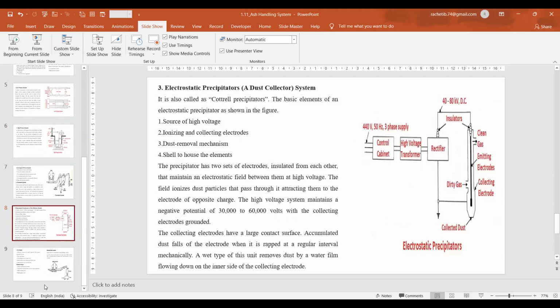Now the most important one, the electrostatic precipitator, which has an electric field causing ionization of the ash while flowing from the economizer and air heater into the electrostatic precipitator. The flue gases separate into positive and negative ions, ash, with the help of this corona effect, and are collected into the bottom hoppers.